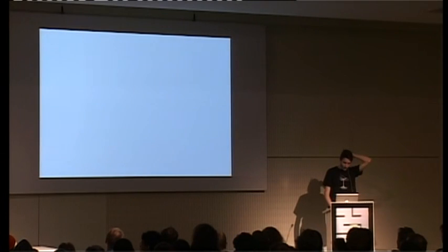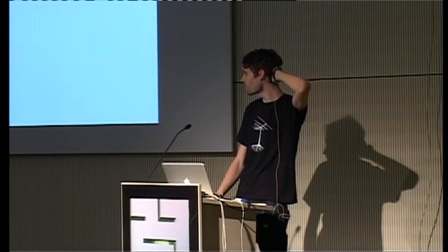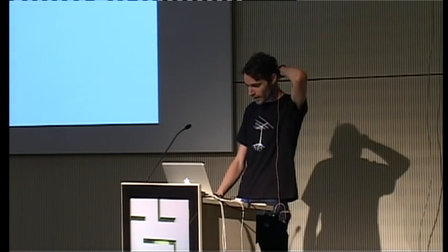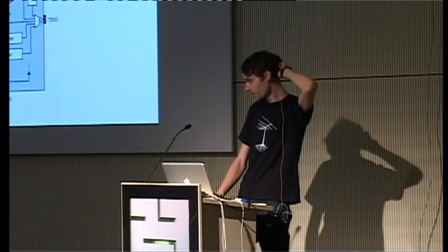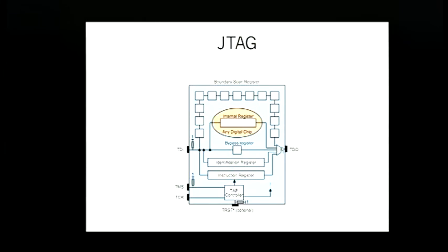Yeah, so that's serial. So assuming, let's say, you didn't get something interesting, you weren't able to get to the code or dump the firmware or something like that, you might move on to JTAG. I'm going to explain JTAG really briefly, just so you understand what the pins are for. So we have 4 pins here. We have input, TDI, we have output, TDO, TCK, which is clock, and TMS, which controls the state of the tap controller.